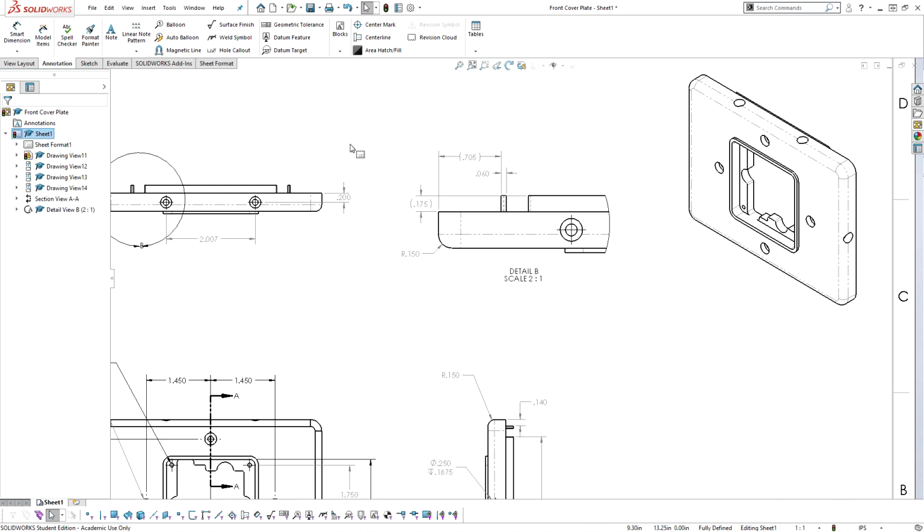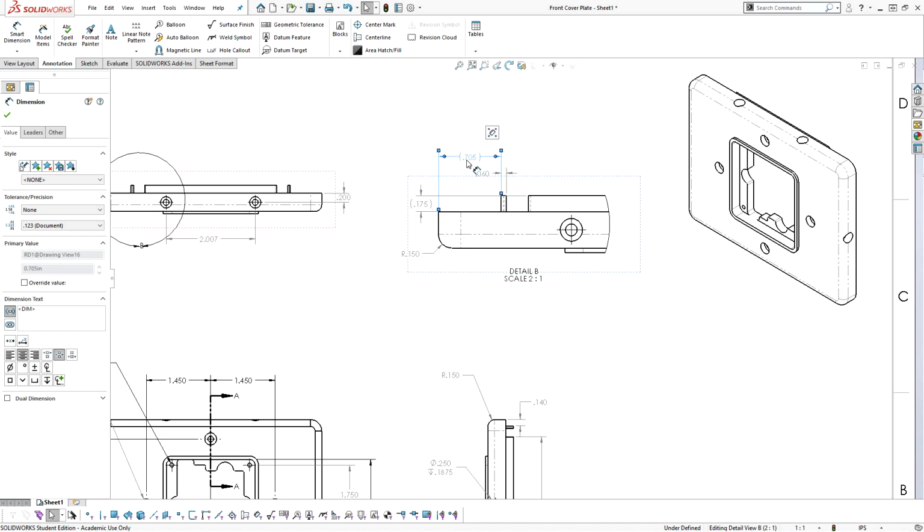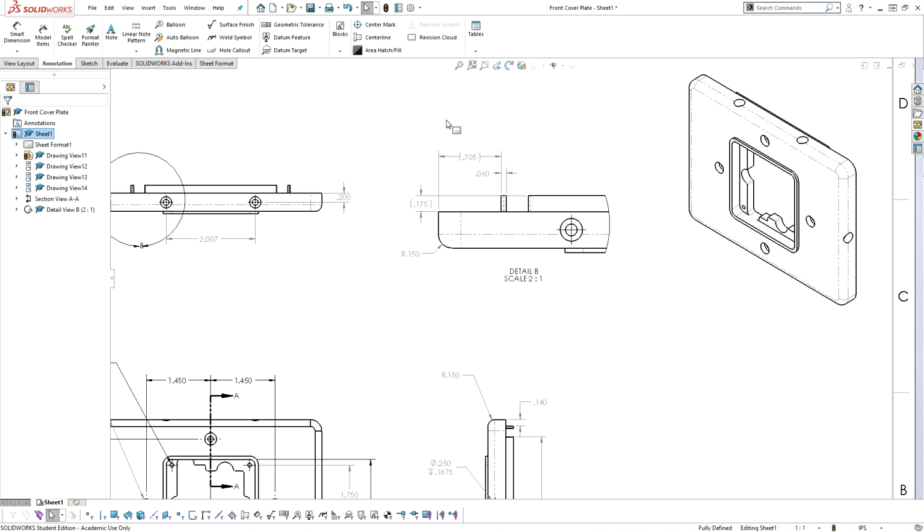I also want to remind you that when you're dimensioning these things, you have mouse gestures. If you right click and go up, that's your smart dimension. That's a hole dimension. That's your, for assemblies, that's your circle text, your items, and that's for notes. I also want to show you that I noticed that they're telling you to hit the parentheses over here for adding your reference parentheses. You don't need to go all the way over there. There's a quicker gesture. You select the text and go up to this box and you can add the parentheses right there. Okay?